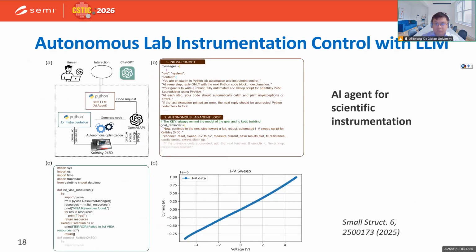What's more, we can use an AI agent. What AI agent means is that you use a large language model, with natural language, to interact with an API, like OpenAI, Kimi, Moonshot, DeepSeek. Then this API, with a proper prompt, can design the Python code itself. It uses this Python code to interact with the instrument and collect the errors from the instrument. In this case, it's a closed loop method. So we can have the IV sweep in 10 minutes without any human interaction. We only design the prompt and the Python code for the AI agent.